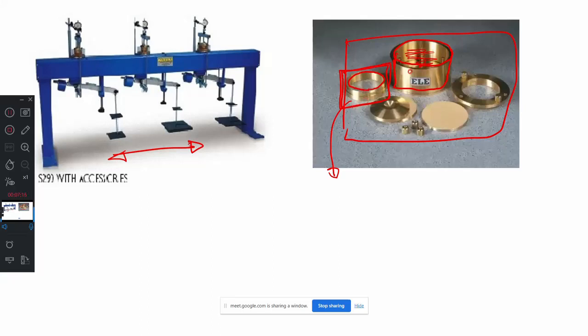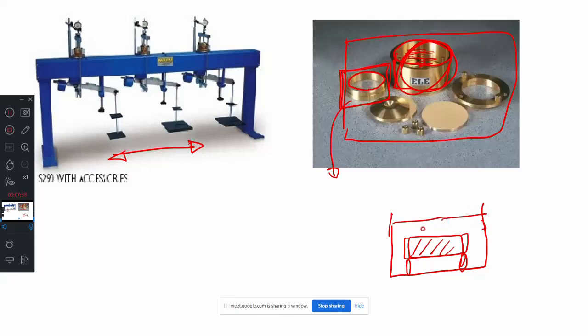Then that soil you can bring here. Then the arrangement will be something like this. This is your soil, whether it is disturbed or undisturbed soil. Then this is your container, and this assembly we will put in the big container. This is your big container. In that one we will put it, and we will make some arrangement here so that the water will be completely filled. This is your water. From top and bottom, water is there. Then above this soil we will make some arrangement.